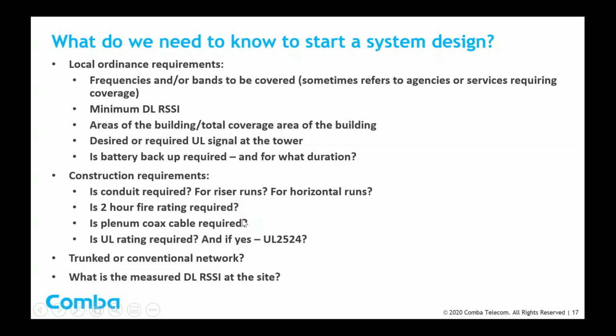Some jurisdictions require it, some don't. Some require it only for the horizontal runs, some require it for the vertical runs as well. Is UL rating required? And if yes, just what we call regular UL, or do they require UL 2524, which is a new UL standard that emerged about a year ago? Is the network trunked or is it a conventional network? What is the measured downlink RSSI at the site?